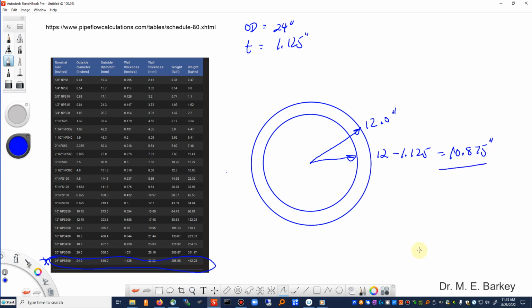So we'll make this mesh in Hypermesh. And for a section of pipe, let's make it 36 inches long. I'm going to first mesh the cross section, then drag that down the z-axis to make this section of pipe.